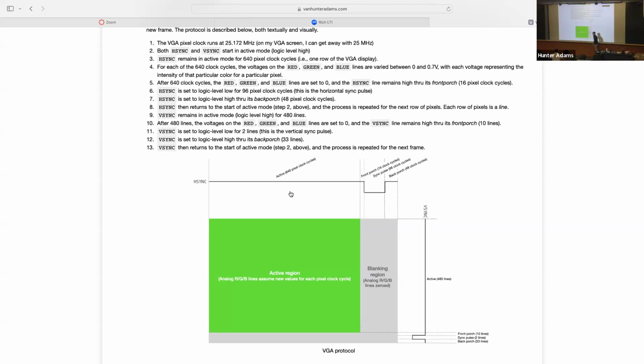This is the motivation for us for driving this screen from this peripheral that I'm going to describe today and over the next couple of days, these PIO coprocessors. What these allow us to do is all of this highly timing-sensitive control input to this screen completely using peripherals that are outside of our CPUs, outside of the ARM processors. The consequence of this is your ARMs, your application code, does not even know that this control input is happening. It costs exactly 0 CPU time for our RP2040s using our VGA driver to control this screen.